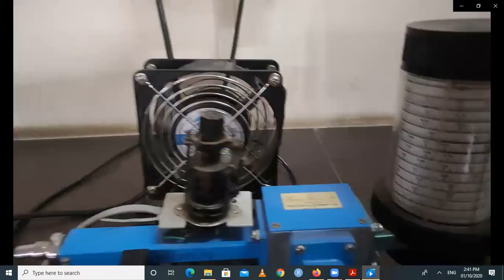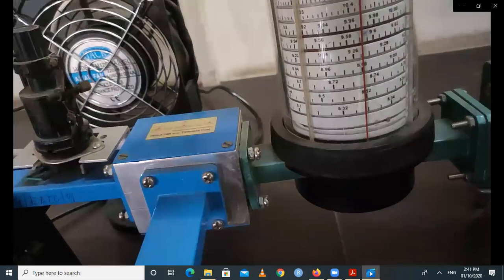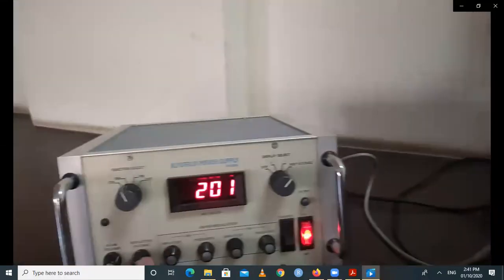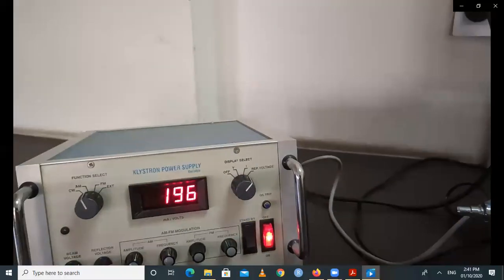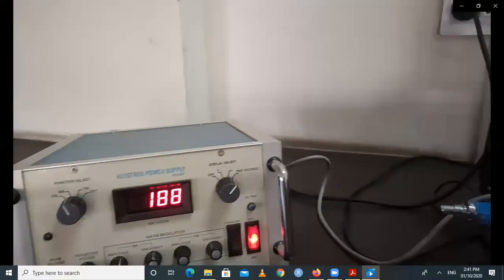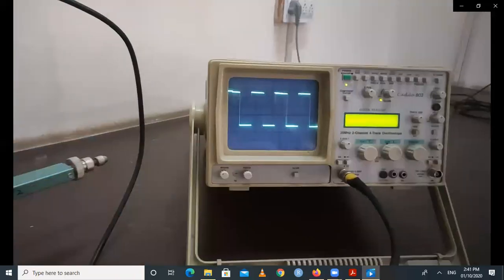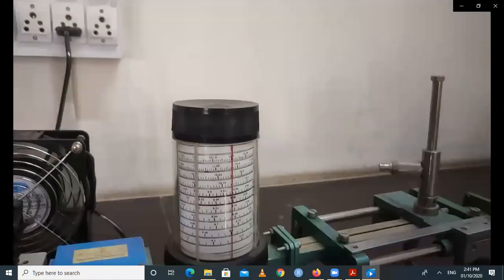So after taking that frequency reading, again you have to deselect this particular frequency meter, means you have to rotate somewhere in left and right side, and after that again you have to reduce this particular repeller voltage for maximum output. So at this voltage 188 I am getting a maximum output here. So this output is nearly equal to 4 multiplied by 0.2 volt. And again I have to find out the frequency.